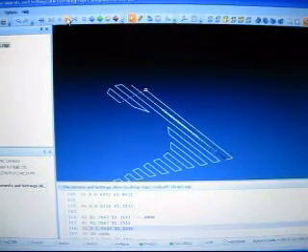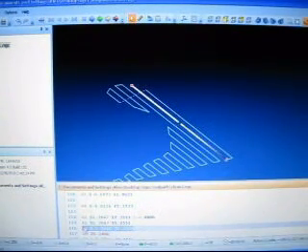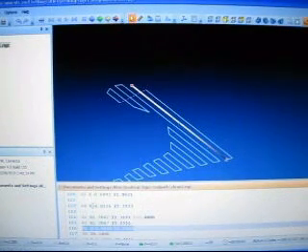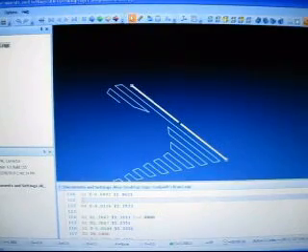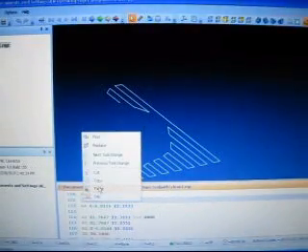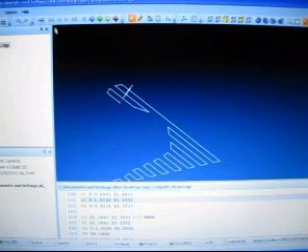But I want it to feed directly to there. So from there, see that rapid motion line in the dotted? I want it to go to there. Okay, from there to there. So that's a coordinate that I need. So I'm going to go ahead and copy that coordinate. Alright. And where I've eliminated the rapid motion, so after this line of code right here, there's this blank space where we eliminated something. I'm pasting that right there. Alright, so that's going to go now where I want it to.